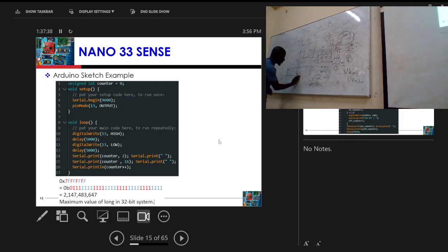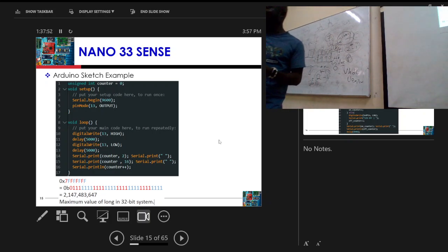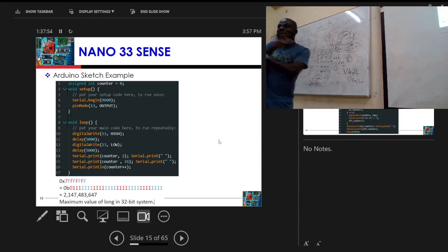So you have it on for a very long time, and then you turn it off completely. But because your eye is so slow, it sees the LED as dimmed, when actually it turned off completely. Because of that short off time, your eye sees it as dimmed without going off completely. That's what your eyes think. But you have actually turned it on, then turned it off completely for a very short amount of time, and then turned it on again. That's how you dim an LED. Simple, right?